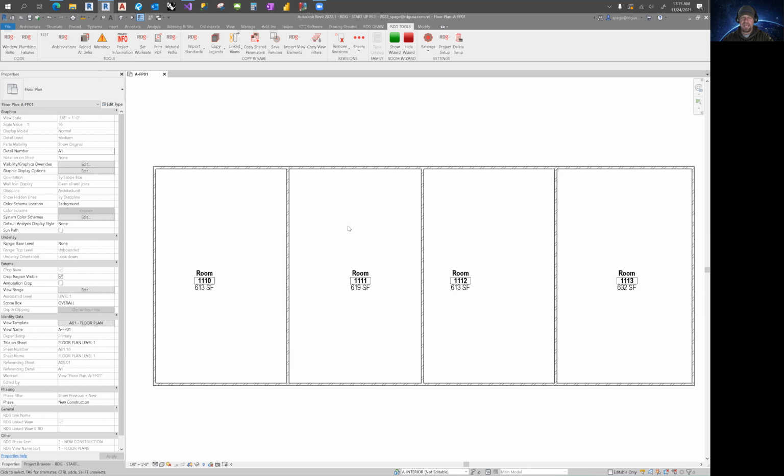We didn't really do that, so we tried to leverage some Dynamo to push values as a one-time thing, but then how do we keep them up to date as we go through without running the Dynamo graph on a weekly basis or whatnot? And so a solution, for the time being anyway, was actually to create an updater that will synchronize parameters.